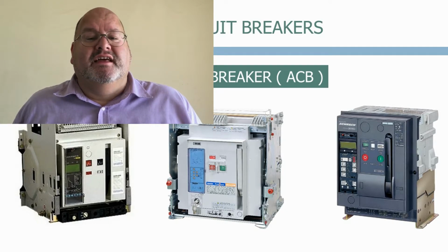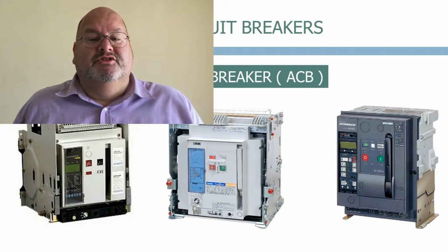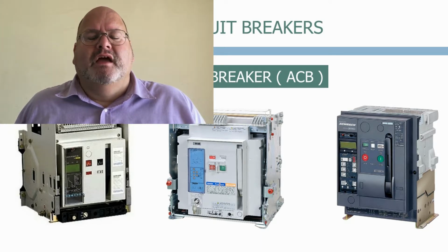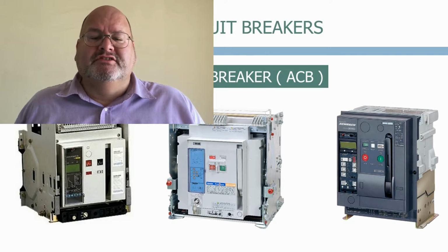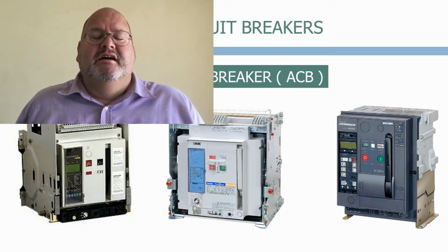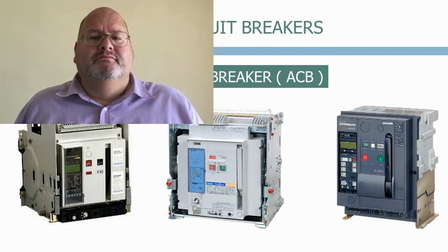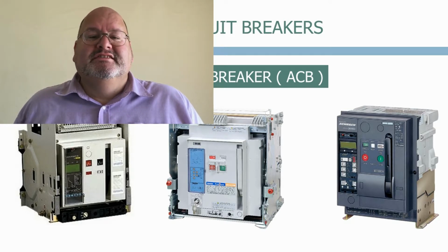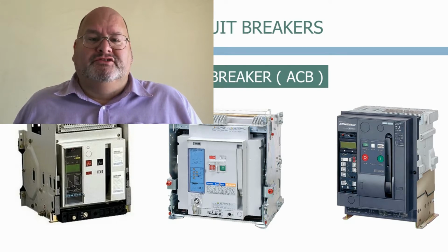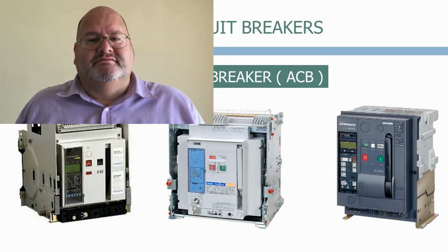Air circuit breakers tend to be used on incomers due to the high rating required and the wide range of time current characteristics available, which allow it to successfully discriminate with all of the equipment farther down the system. They are normally supplied with software packages, which permits all of the curves to be selected and set from a PC via a standard USB port. This makes life a lot easier, as setting ACBs can be quite complex when you have to do full discrimination with other devices.